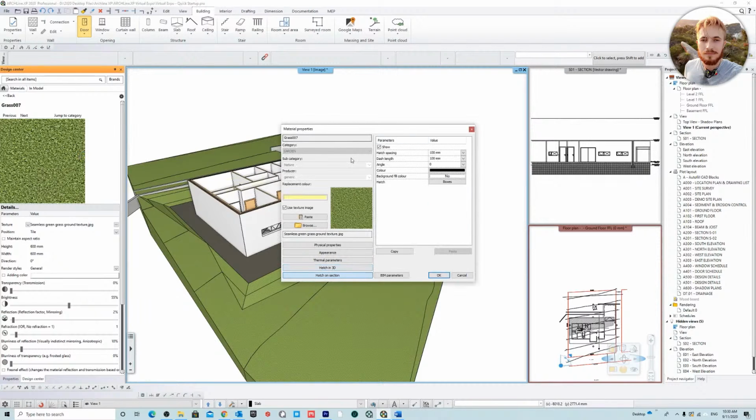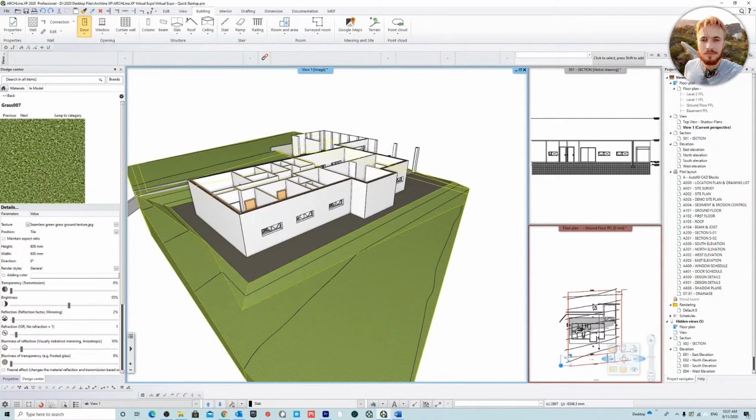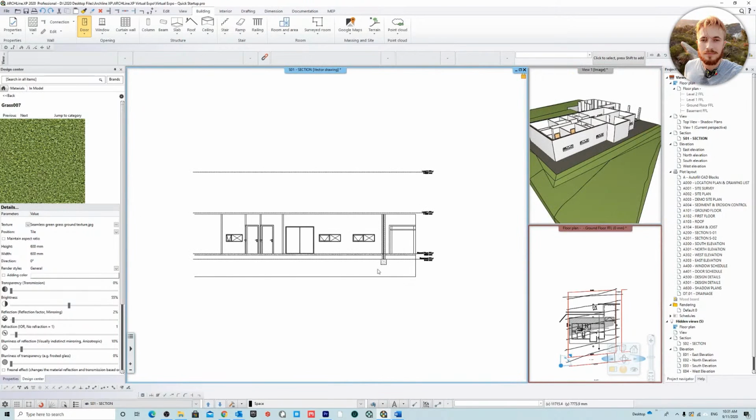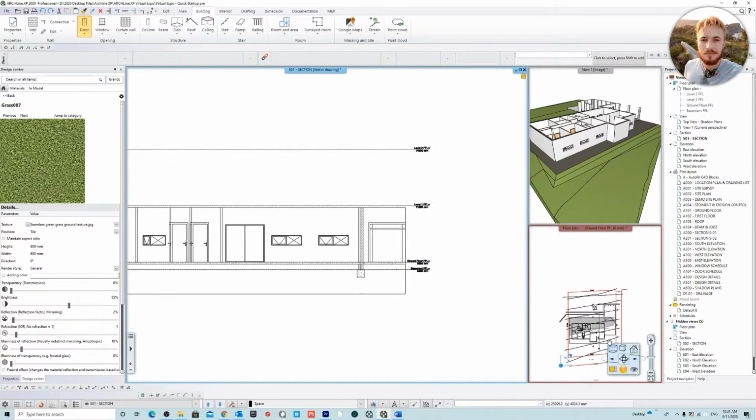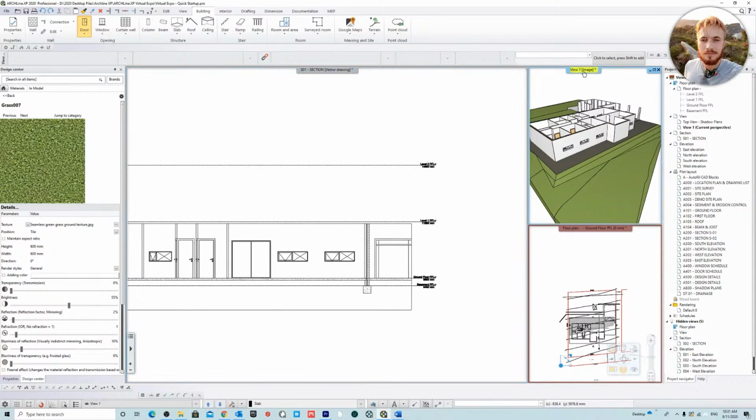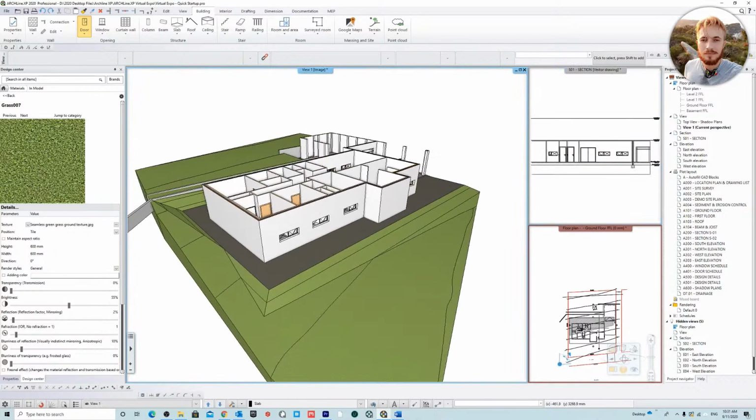So that's why in the section properties, you can either change the types of hatches, but for the moment, I'm actually going to just switch these off because we don't necessarily need to see that for our sections at the moment. And I'm just going to hit rebuild. Okay, so now if you go to your section, you can see there's a nice clean section view that you can use for your documentation. And for this, I'm actually just going to switch it to hidden line removal. Okay, so that pretty much covers it.